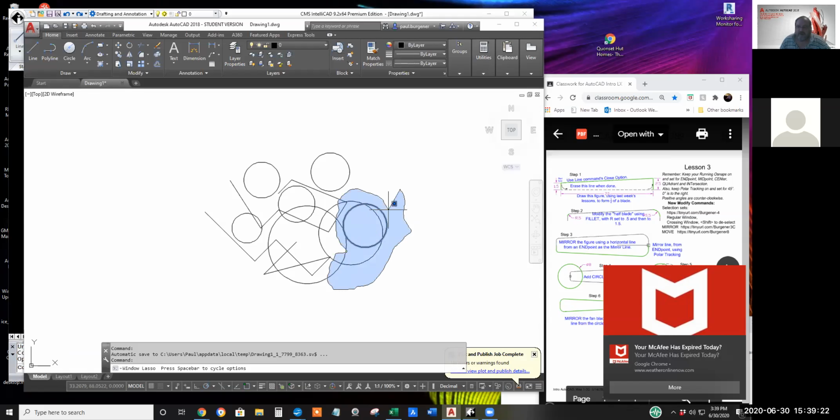What else? There's a fence option. Click erase, type F, enter, and everything that the fence line crosses will be erased. But again, I want you to take from this class the left to right, the right to left, the individual click, and holding the shift key to deselect. Bring back my garbage again. So far, so good.